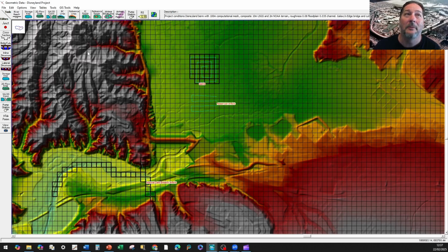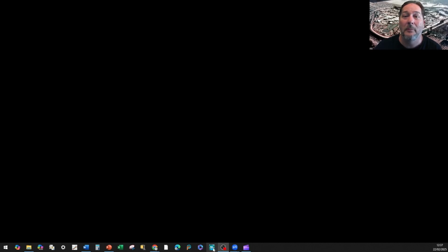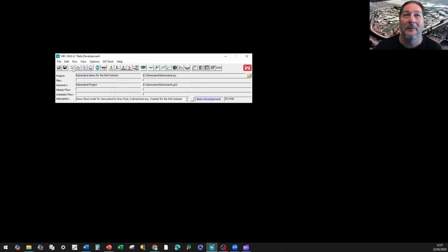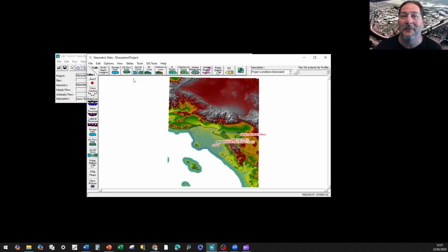And so let's see what happens now when I save this, exit out of HEC-RAS altogether. We should see which cells these ones connect to. So I will file save, exit, come back to HEC-RAS into my model here. I'll open up the geometry. We should see a few of these. I'll delete the ones I'm not going to use, and then we'll proceed with the next boundary conditions.